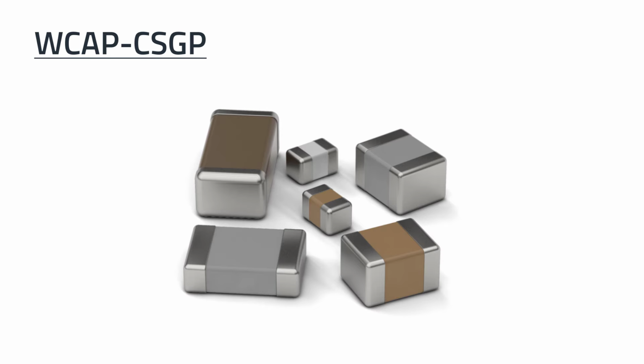This capacitor is an NPO ceramic type, so it offers more stable voltage and temperature behavior compared to the X7R ceramics. When considering these critical factors, such as signal integrity due to the cutoff frequency of the filter and the capacitive load, it's really important to account for parasitic capacitances of the conductor tracks and, if necessary, interface connectors.